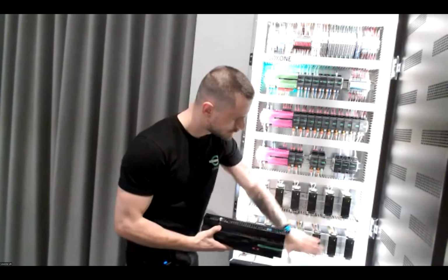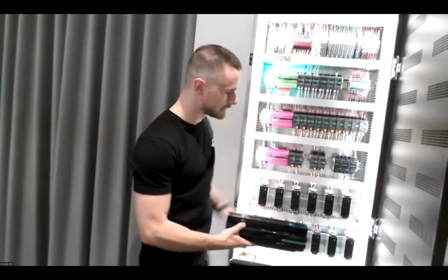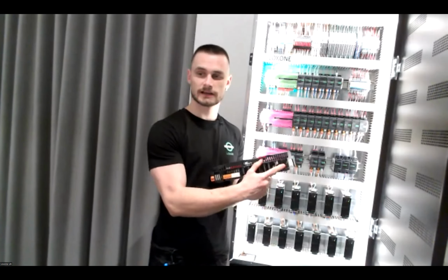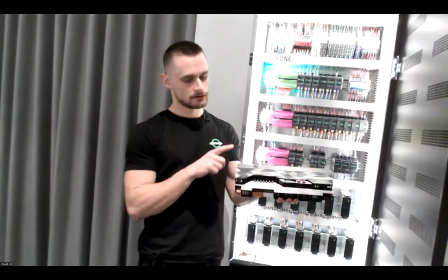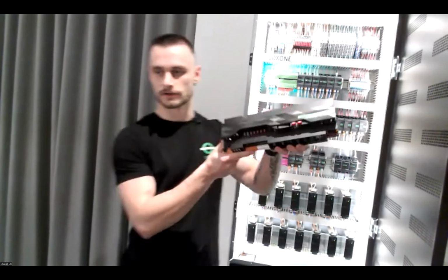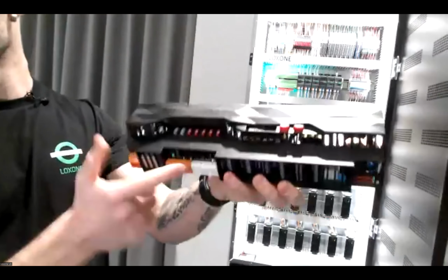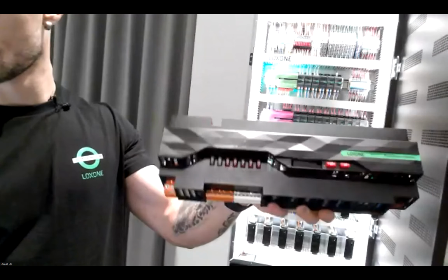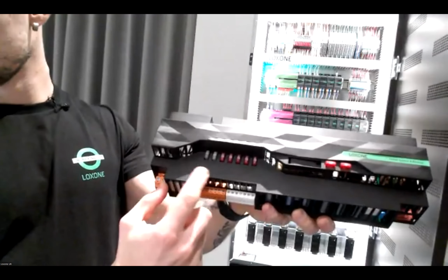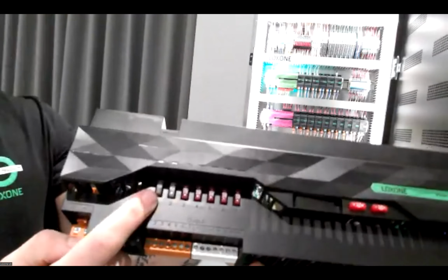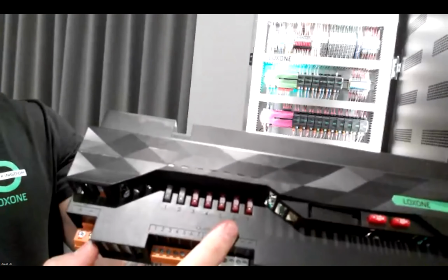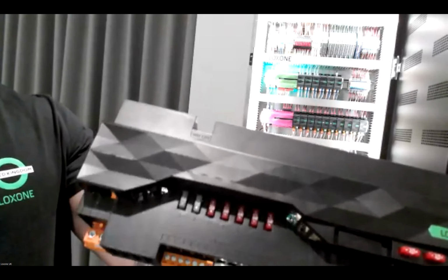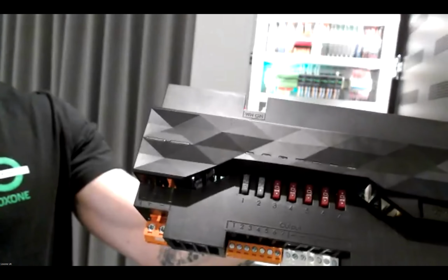As you can see, remove the power supplies here, remove the smaller power supplies, slap in one power supply and backup. We're still going to have that nice separation between our mains and the 24-volt outputs that are going out, because you have mains in, 7 fused 24-volt outputs. You no longer need the blade fuses on top because every single output is going to be fused, and you can fuse different channels with different fuses, obviously.